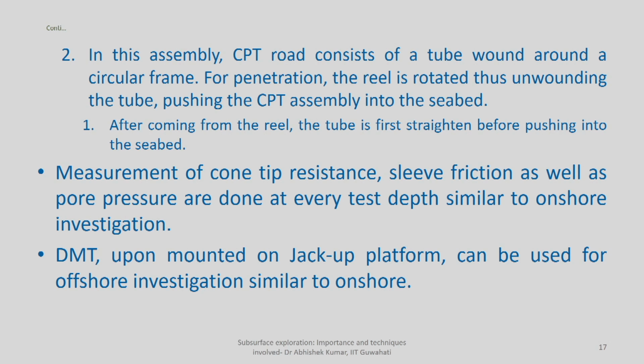Now, the measurement of cone tip resistance, sleeve friction as well as pore water pressure can be done at every depth or as continuous recording, both. The DMT dilatometer, as I mentioned, can be done from the surface assembly by means of mounting on jack-up platforms, which are almost like a fixed platform from which you can do it. So, any possible fluctuation in water level will not affect your DMT measurement, similar to your onshore investigation.